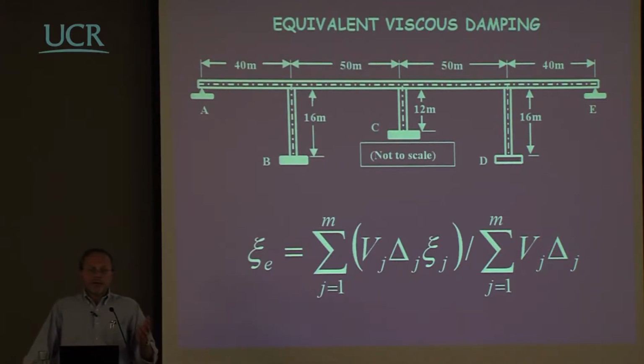So it has been discussed that if the displacement is the same, certainly the ductility demand at the different piers is different. And if this is the case, clearly it doesn't make any sense to define one single force reduction factor that should apply to abutments, piers, and everything.